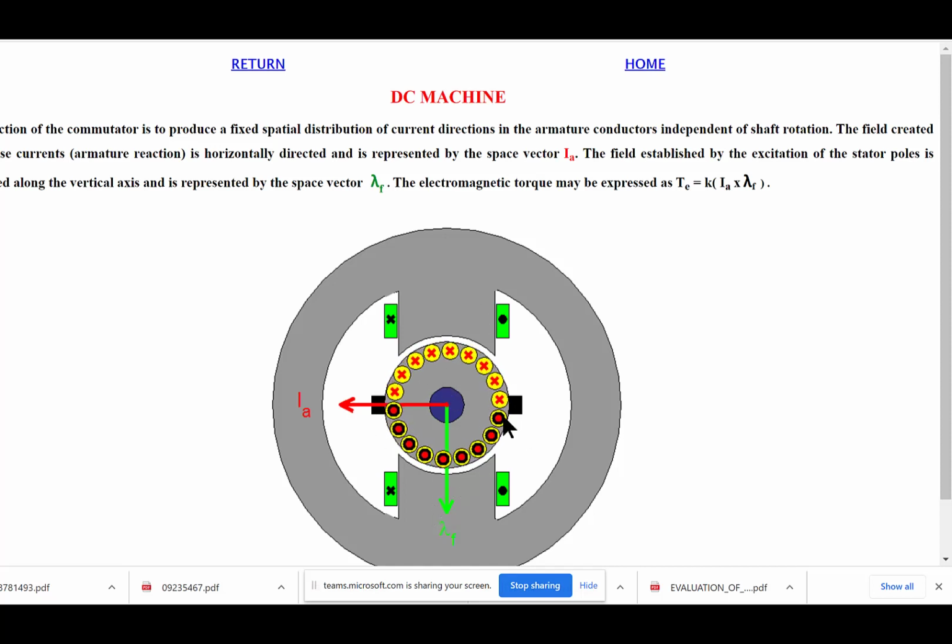The rotor's moving, but for a machine, a motor or a generator, to work and produce torque, or use torque to generate a voltage, you've got to maintain a fixed angle between the field MMF and the rotor MMF. The rotor is the armature. So the winding is armature on the rotor, and the winding is field on the stator.